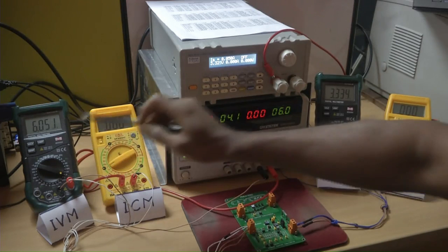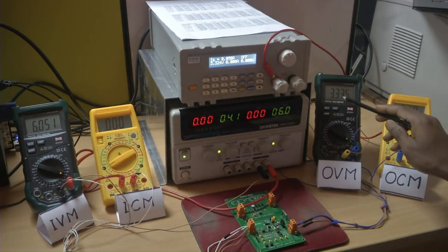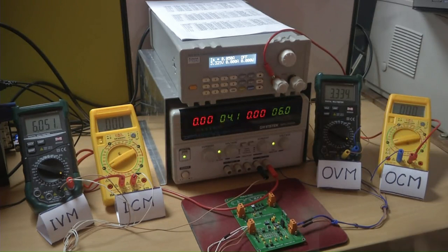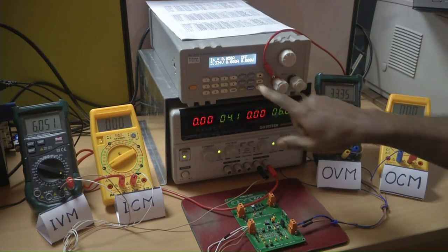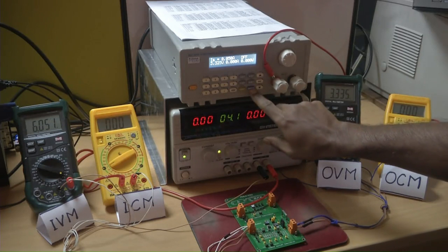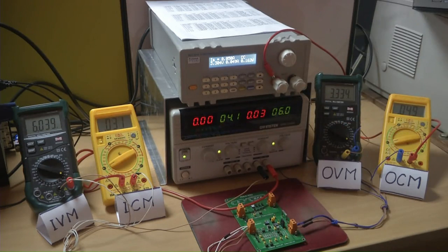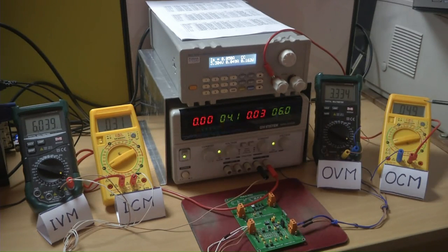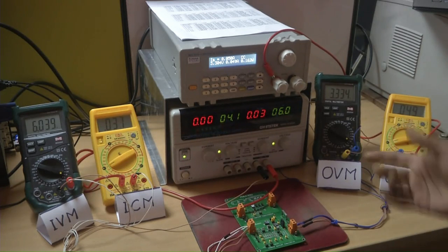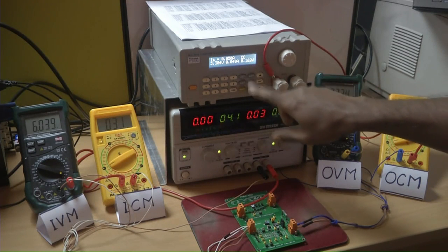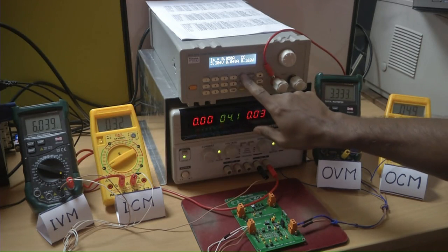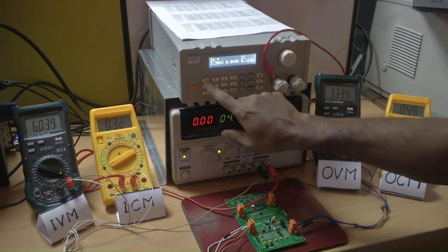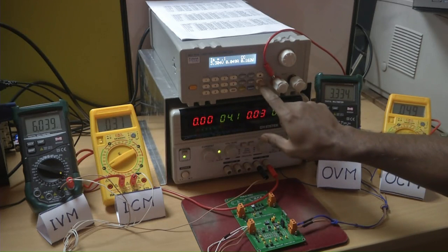What you have here is the usual setup, you have a current electronic load which is placed on top of the power supply. Left side is the input voltage and input current, and the right side is the output voltage and the output current. What we are performing in this experiment is to understand the power loss, essentially what is the power being delivered at the input and what is the power delivered at the output. You just want to find out the difference between the two, and if you do this experiment you understand many related things with respect to efficiency and so on.